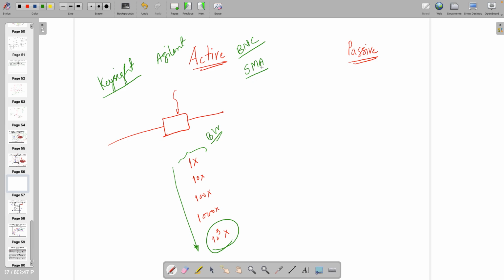If you have seen that connector, golden color, this one is aluminum colored or steel colored, right? So that BNC has lower bandwidth. Sorry, I should not say lower impedance, but lower bandwidth. SMA has very high bandwidth. So I do not want to decrease the bandwidth with this particular feature. I want to have higher and higher bandwidth at higher impedance.